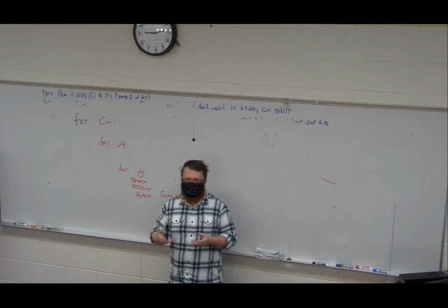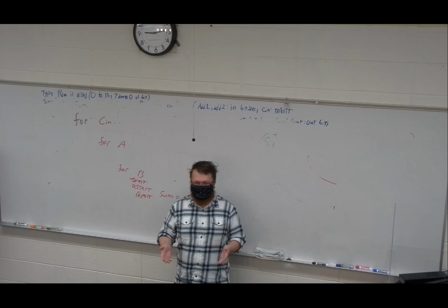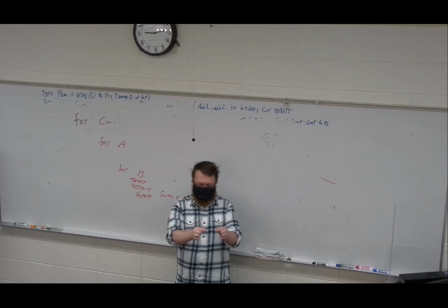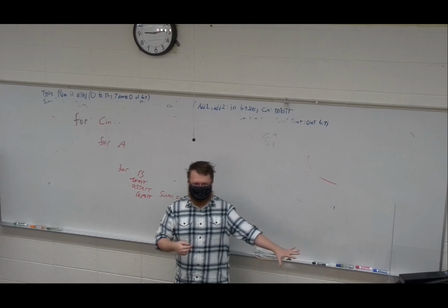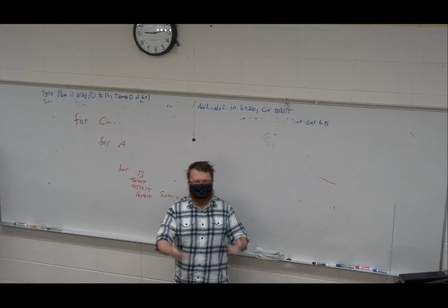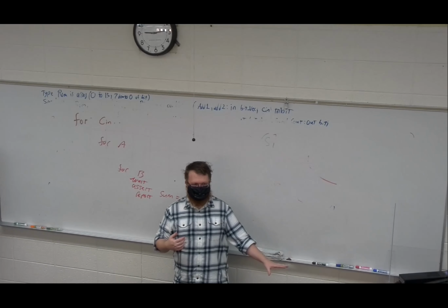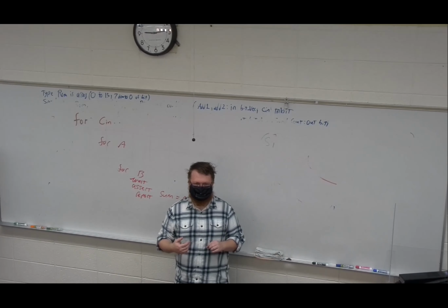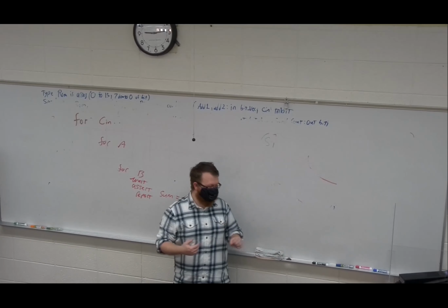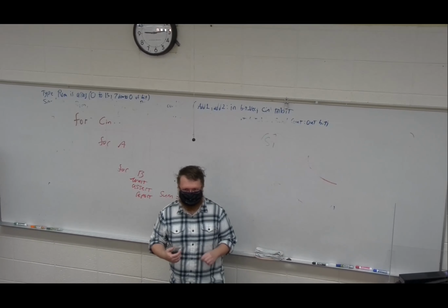The soft core allows you to have what we call probes. Probes are like when you take an oscilloscope and measure one point versus another, but these are digital probes. They can send data back to Vivado, and you can actually view the signals on your FPGA in real time. I will show you how to do that today.